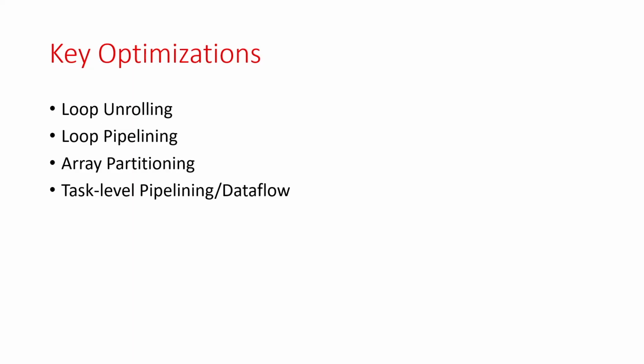In the context of high level synthesis, as I have already discussed, for behavior where there is no array and loop, high level synthesis can synthesize things into hardware efficiently. But in the presence of loops and arrays, we found that high level synthesis may not always give you the best hardware. So, you need to understand how to apply the loop-related optimizations as well as the array-related optimizations of the high level synthesis tool efficiently for efficient generation of hardware.